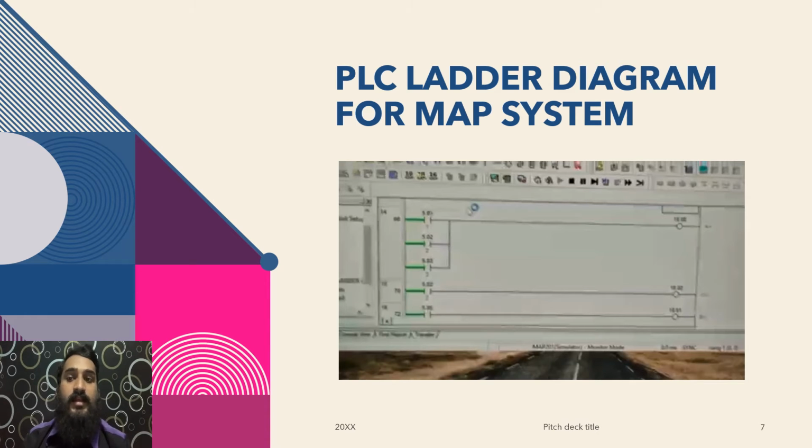For the ladder diagram, firstly we need to set on the push button, and push button 1 will release, and then set on the sensor A1 to activate after the cylinder fully extends, and then the same goes to sensor C1, which will activate and cylinder C will extend,